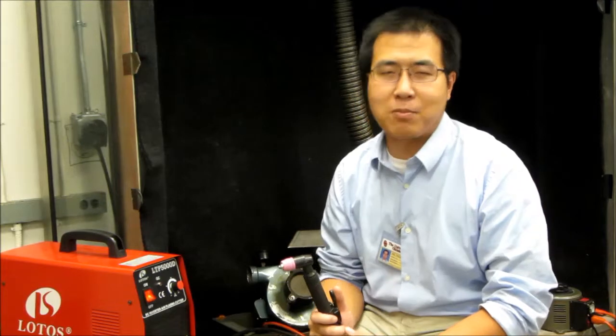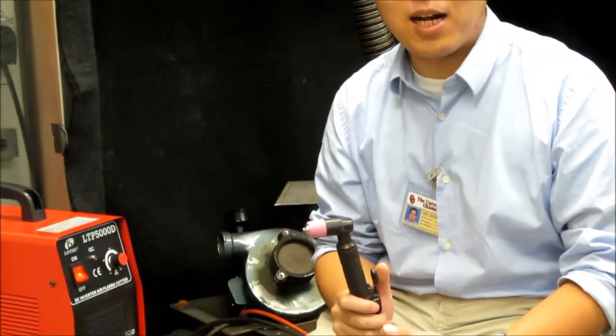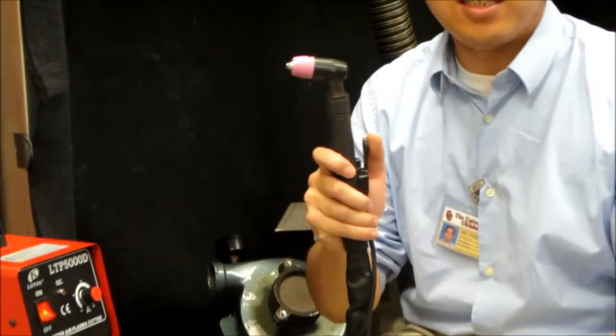Plasma cutting is a thermal cutting process that's very commonly seen in oil and gas, manufacturing and construction industry. It is very useful when you cut thick and heavy stainless steel. The idea of plasma cutting actually comes from plasma welding in the 80s. The principle is by shooting out air or inert gas from the nozzle and applying high current to the nozzle to form an electric arc. The arc will then plasmatize the air. The plasma arc will melt the metals along the line, just like this.